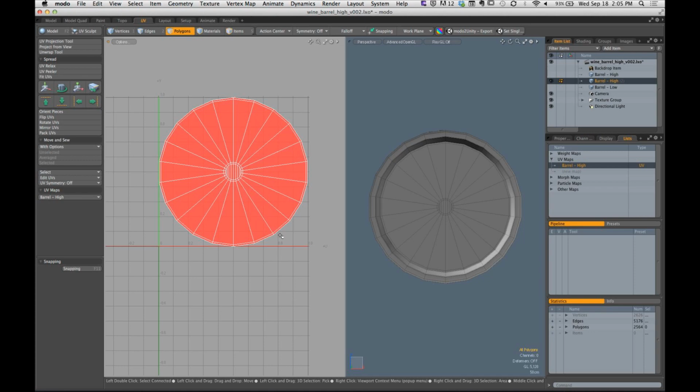So we really, really need to make sure that all sides of my wine barrel are dialed and looking perfect, okay? If I know beyond any reasonable doubt the gamer is never going to see the bottom of the wine barrel, then the bottom and the top are going to be the same, right? We're going to make this prop as if it's going to be seen from all angles. So I'm going to separate out my UV islands to ensure that I can texture the top and the bottom differently. Now, last week we talked about some strategies that will allow us to do this. How can I very quickly separate those two overlapping UV islands apart from one another?